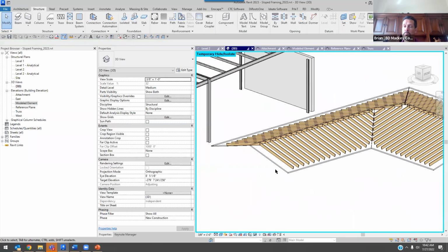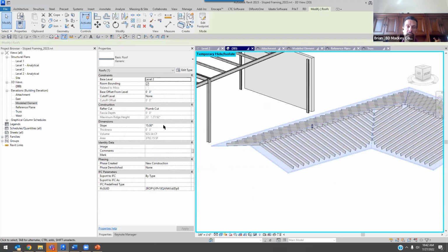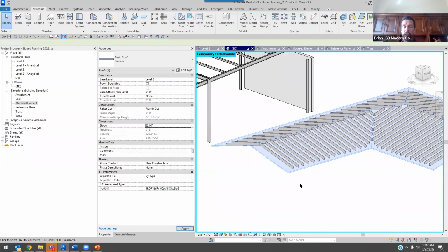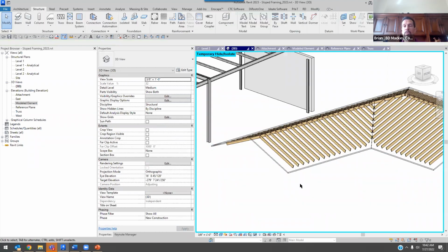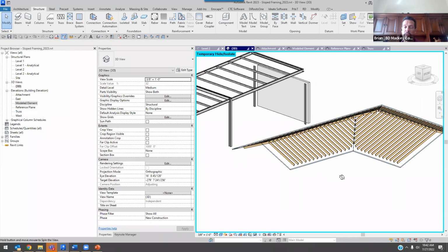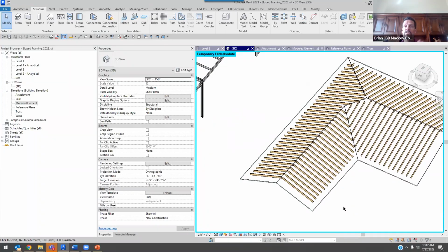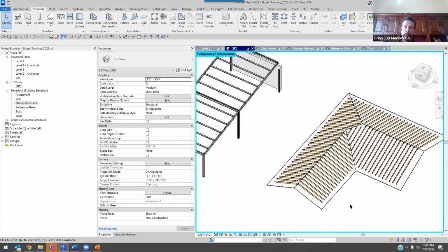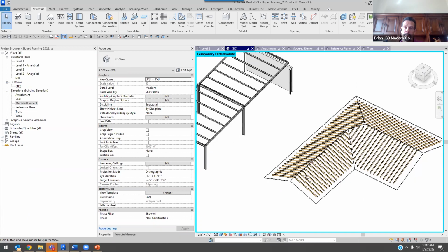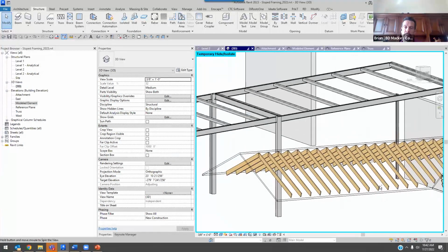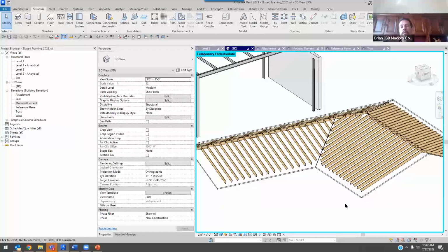It's all still there. And if I take this roof slope and it's like, ooh, that's not a 15-degree slope, let's do a 22-degree slope, right? I change the slope. All of those columns are going along for the ride. The beams are associated to the columns with the start attachment and end attachment. And then there you go, my beam systems are then associated to that. So kind of a nice little scenario there to go through and do that slope framing.